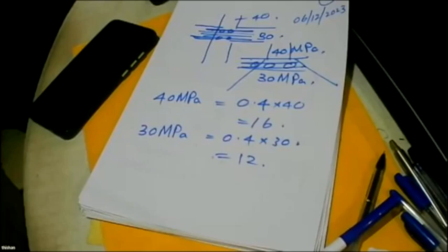These days we are doing a project where, what is the general capacity of a 1,200 pile? 6,000 kilonewtons. What is the general capacity of a 1,500 pile? 10,500 kilonewtons. But in this particular project, our 1,200 piles of 40 megapascal will carry 11,000 kilonewtons, nearly twice, and our 1,500 millimeter piles will carry 17,000 kilonewtons, all with 40 megapascal concrete for the pile shaft, with 0.7% maximum reinforcement in the pile.